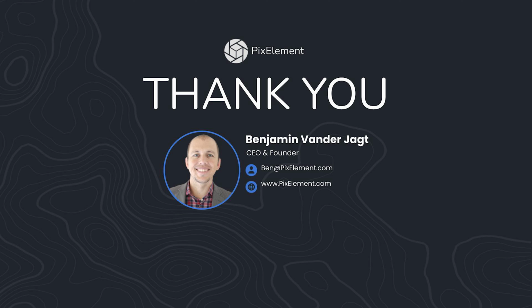Resolution, you brought up another good point. That is a problem, because the point spacing of LiDAR data may be different than, for example, the GSD of the imagery. So when we're building depth maps from the LiDAR data and fusing it, you've got LiDAR data with a specific density or resolution versus the imagery, and it creates some problems.